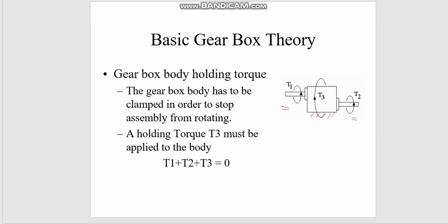So we need to calculate what is the torque that the body of the gear actually experiences. We call it T3 or tau 3. Knowing how much torque is being applied on the body, we can size up the bolt or the holding mechanism to hold the gearbox in place, right?